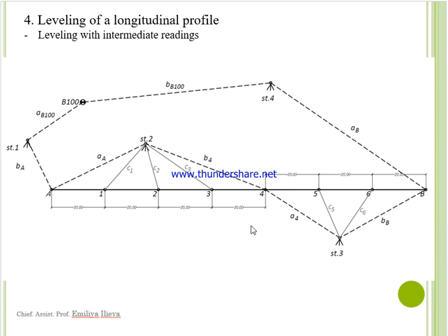They have been set out on the terrain, and now we need to determine the elevations of all of these detailed points. When we have many points to level, it is not appropriate to use the standard leveling, which you know already, because it requires many measurements and it takes a very long time.